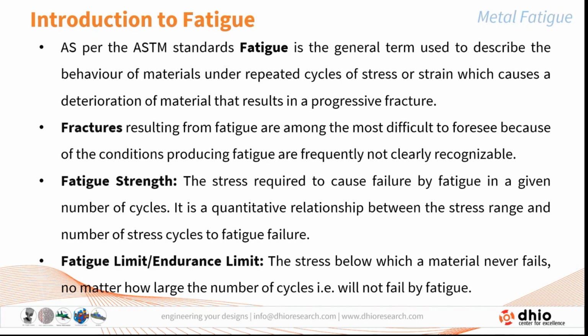Then we have the fatigue limit or the endurance limit, which is one of the properties of the material. It is the stress below which the material never fails, no matter how large the number of cycles. Such a material, when induced with a stress level below this, does not fail for any number of cycles. That particular value of stress is called the fatigue limit or the endurance limit.